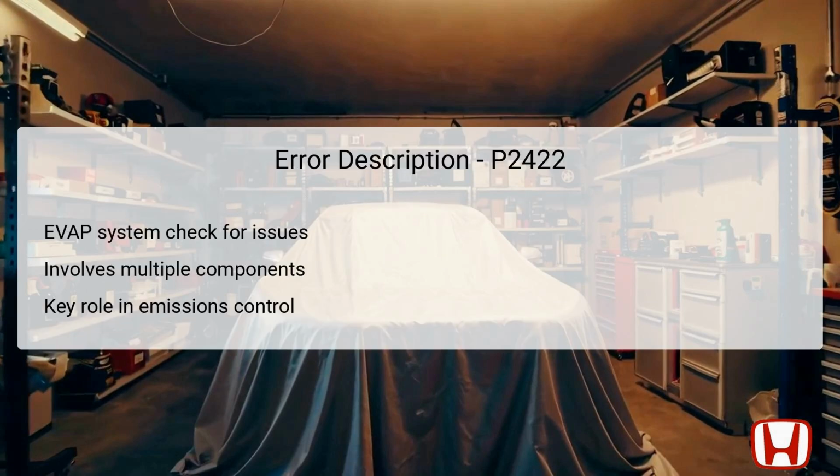The error code P2422 indicates that the EVAP canister vent shut valve is stuck in a closed position. This component plays a crucial role by regulating the release of fuel vapors from the fuel system to the engine for combustion. Typically located near the EVAP canister, the shut valve prevents vapors from escaping into the atmosphere when the vehicle is not in operation. A malfunction affects the entire EVAP system's ability to function properly, leading to increased hydrocarbon emissions.